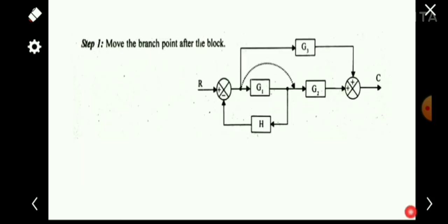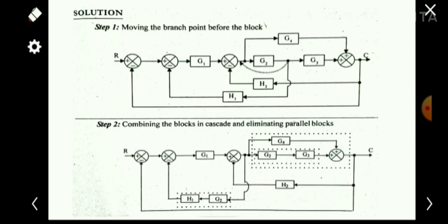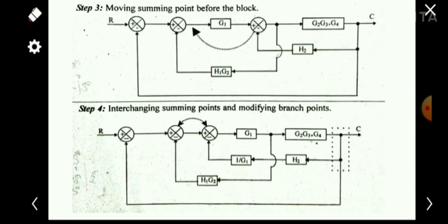Okay, so likewise here, in our problem we are moving a summing point before this G1. So we have to add a 1 by G1 in this line.